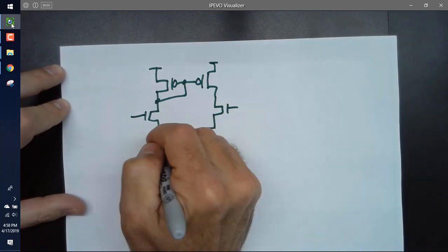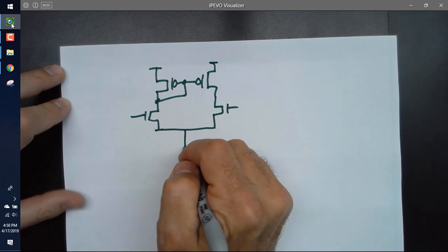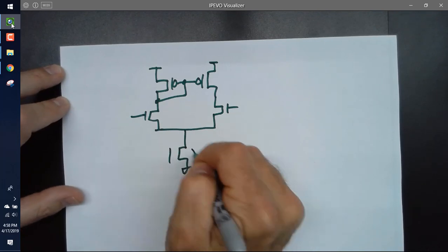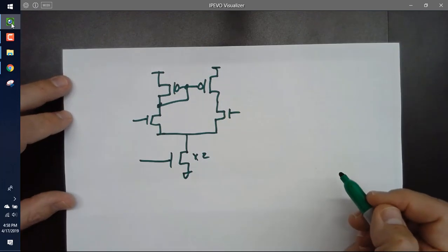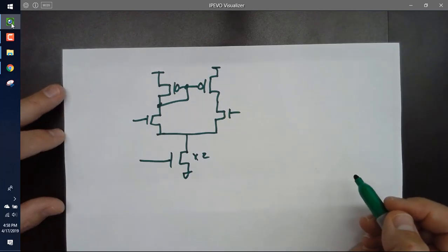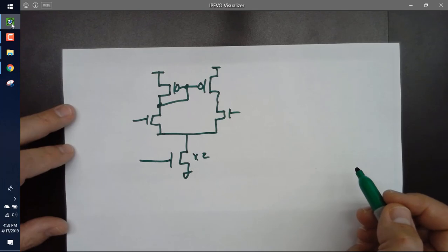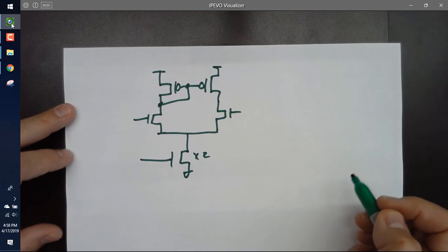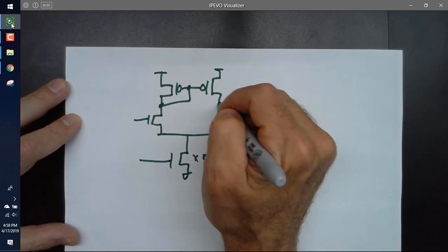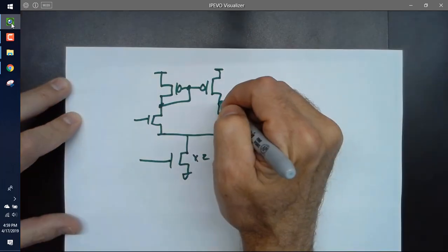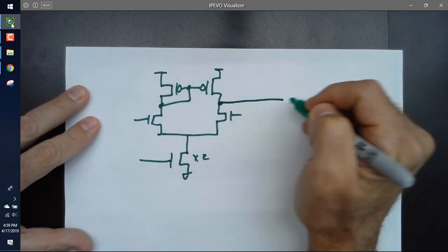Okay, so I go here, and then I come down, and I'll keep this. I'm not going to use cascodes. Why? Well, I can use cascodes, but then if I'm going to do that, I need really small overdrive voltages, like tens of millivolts of overdrive, okay? So then I'm going to go over here, just real basic topology.